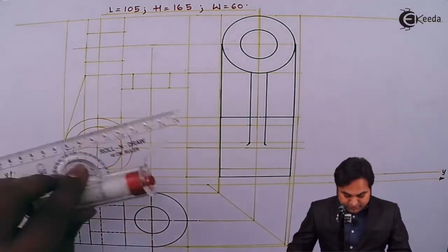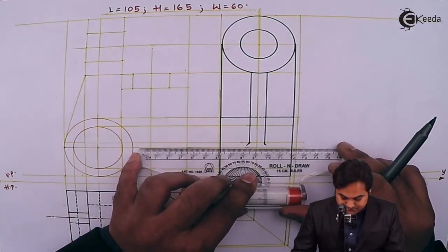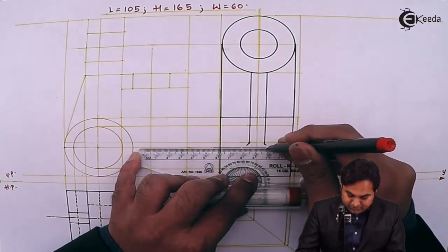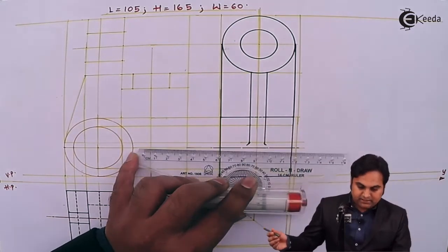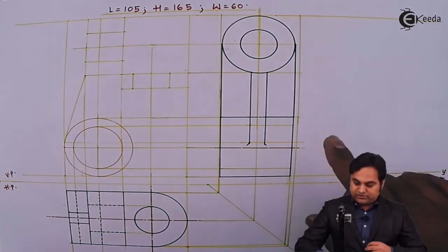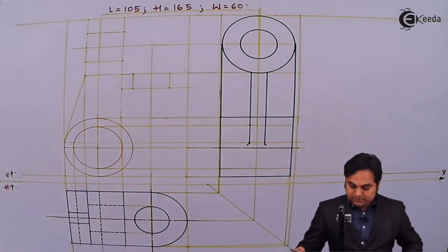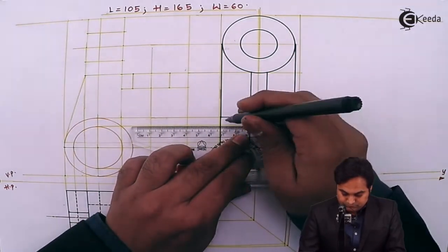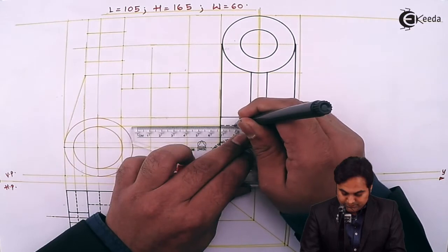So drawing this center line first, it should be medium dark, remember, so that is why I am using a red color which indicates medium dark line, and whatever I have drawn in black, that is the dark portion, so you have to just distinguish between them. Next, the hidden circle, it is throughout the width.